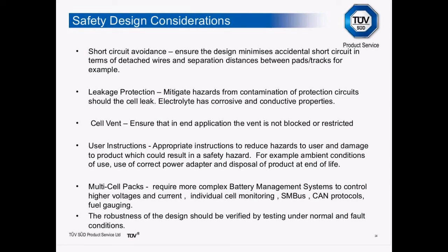For example, identifying the maximum ambient conditions of use for the product, identifying the correct battery charger or power adapter to use, and giving details of the correct disposal of the product at the end of its life. So, for example, not to place it in a compactor or something like that where it could get shorted out and crushed, or not to throw it on a fire. So then there's obviously the explosion hazard.